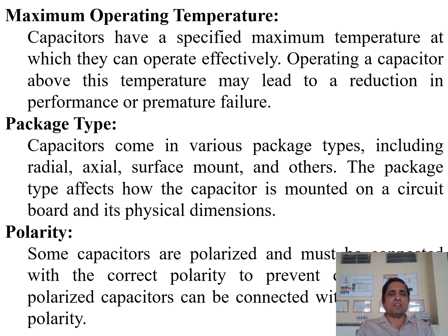Minimum operating temperature and maximum operating temperature. The maximum operating temperature specifies how much maximum temperature the capacitors can tolerate. If you try to operate the capacitors above that maximum operating temperature, they will be damaged. Then package type. Different types of packaging techniques are used for manufacturing of capacitors. So different packages are radial, axial, surface mount and others.